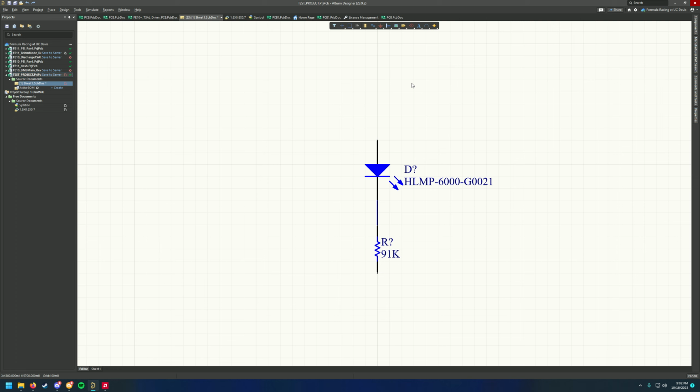And then I need a power source and I need ground. So that's when you probably want to use the toolbar. I don't know the shortcut. There probably is one though. So all of these little buttons, if you long press them, you'll get a larger option menu. So I'm going to put ground down here. So you see this little ground symbol. If I click that, it'll give me a ground port here. So I'm going to connect this to ground.